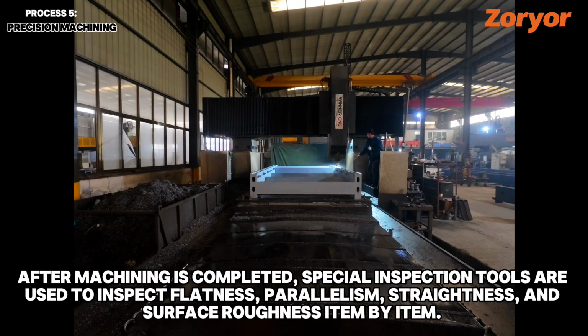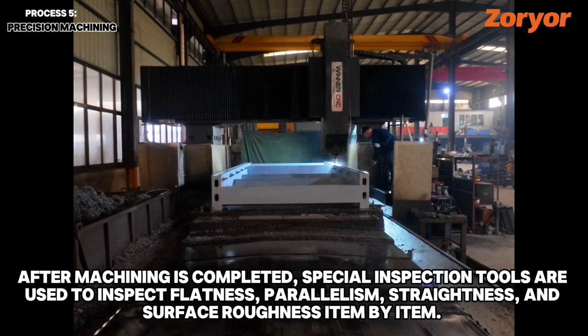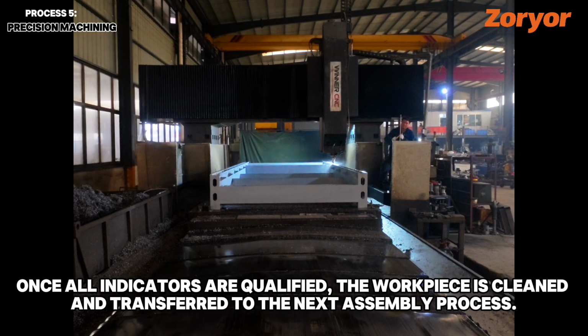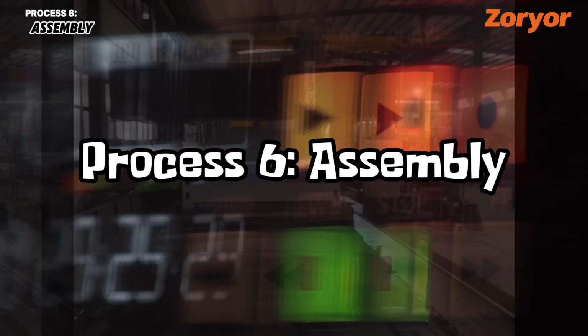After machining is completed, special inspection tools are used to inspect flatness, parallelism, straightness, and surface roughness item by item. Once all indicators are qualified, the workpiece is cleaned and transferred to the next assembly process.